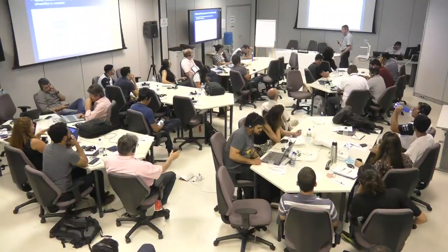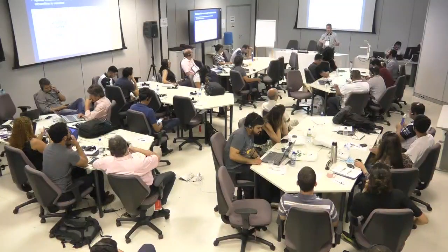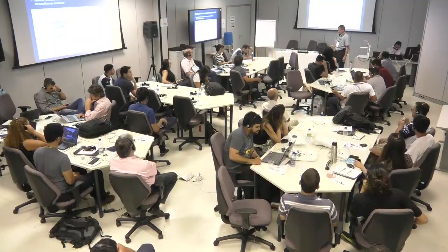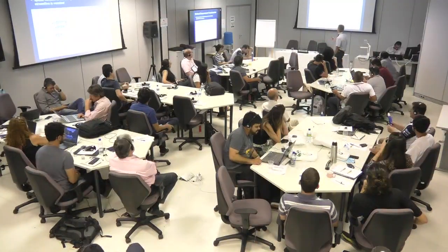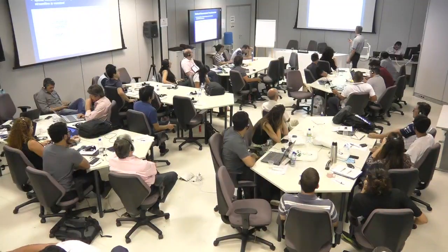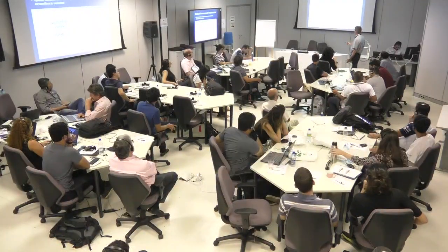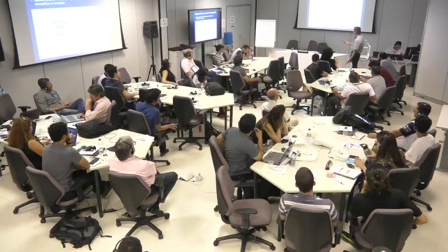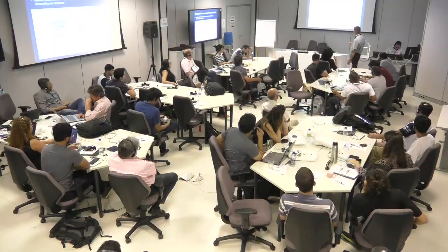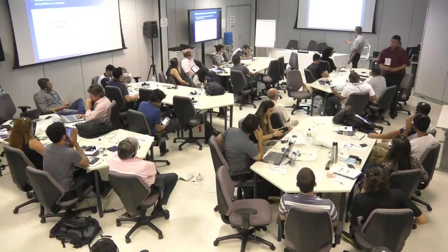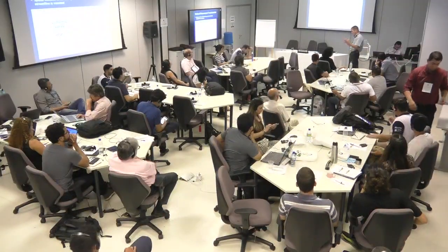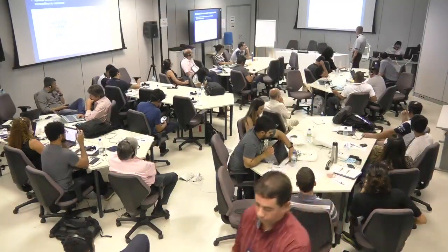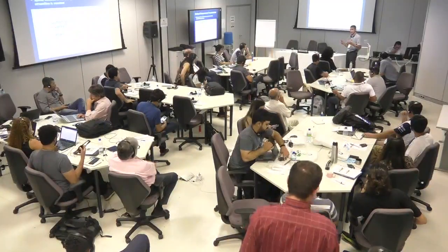So spatially, it could vary, just depending on the shape of the channel and things, much more than the suspended sediment. Here you see it varies uniformly, or is uniform, consistent, or kind of erratic or unpredictable. That is the mean bed load transport on the y-axis and cross-section distance on the x-axis. So it's just giving you 4 different scenarios of how the bed load could move. And there's a number of others, but it gives you a flavor for that. It's a bit different than the suspended sediment.